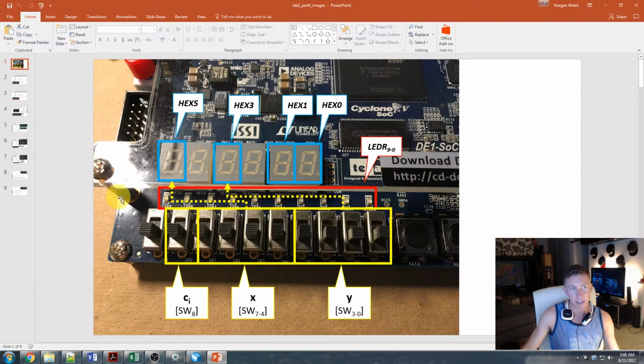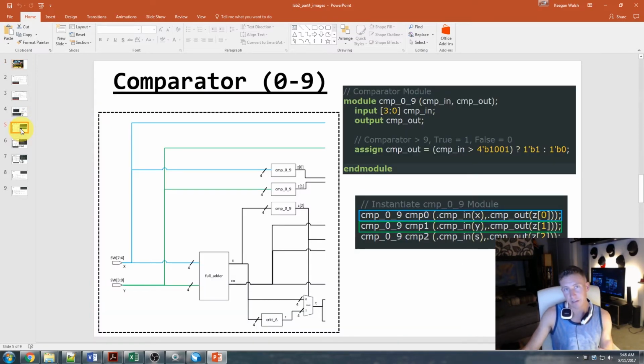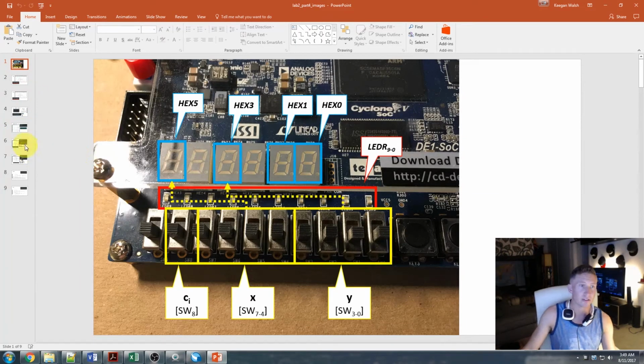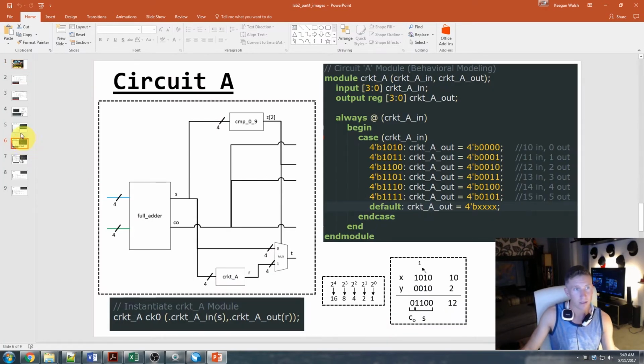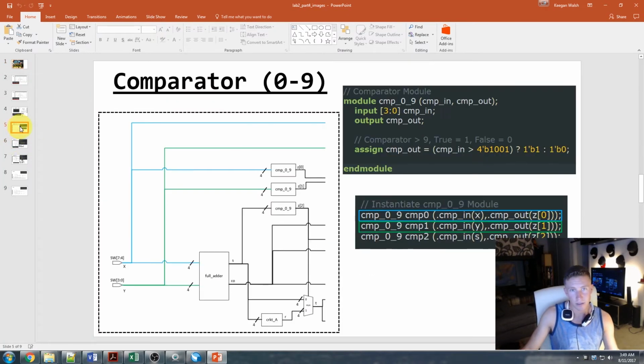When we get to 10, we actually need this to go back to a 0, so almost wrap around, and then this to be a 1, right? So, I mean, it doesn't sound too complex, but again, we're going to need some additional circuitry to make it happen. So just keep that one in the back of your mind. So keep that 5th bit and kind of that idea of needing to wrap that hex 0 when we get to larger sums.